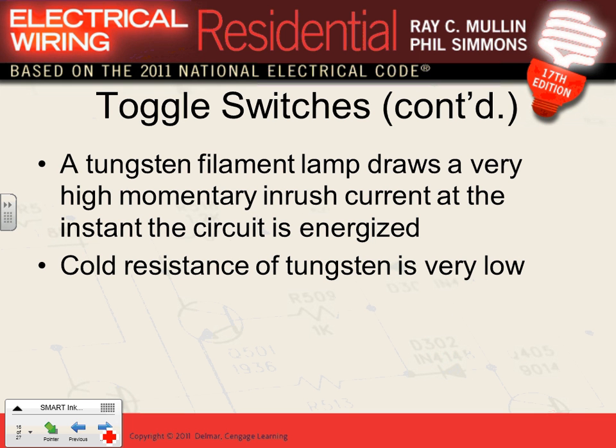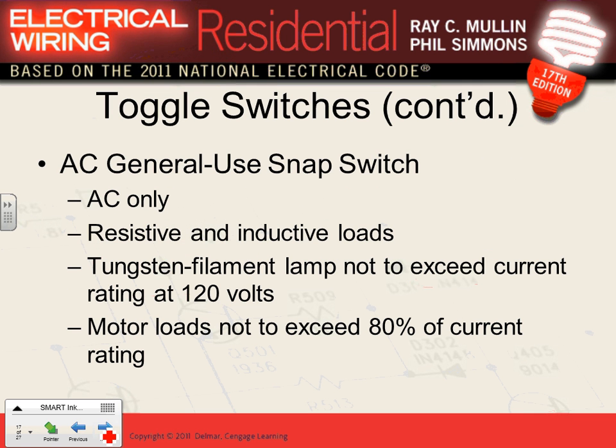Because of resistance, you guys, did you do the experiment with Gary where you tried to measure the inrush on an incandescent lamp in the first quarter? You see how an incandescent lamp sucks almost 10 times more current when it starts, because the cold resistance is very low. The cold resistance before it heats up and glows is very low. If you do this, what does that do to the switch? It will heat your switches.